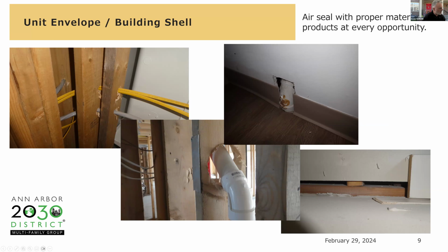Here's a piece of plumbing on the interior where it didn't allow the drywall to come down and through. Here, have a drywaller use drywall mud to pack in around that. Or you could also use closed cell spray foam, but that's not going to look as nice.